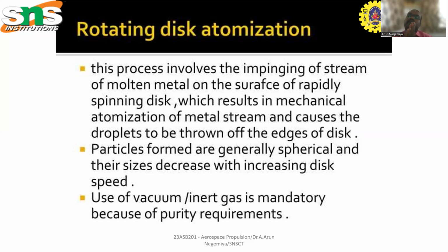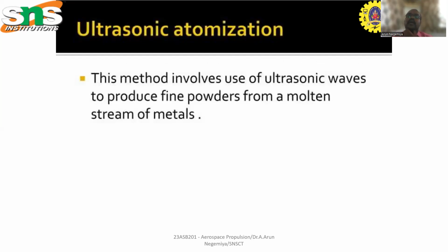One will be rotated in clockwise direction, and the other in counterclockwise direction. During this process, gas will be sprayed over the disk. Suddenly the molten metal is cooled, and it will fill inside the disk. Finally, we will get tiny particles from the molten metal.